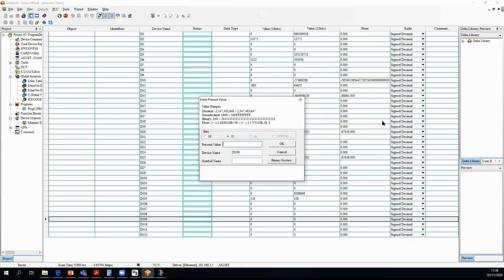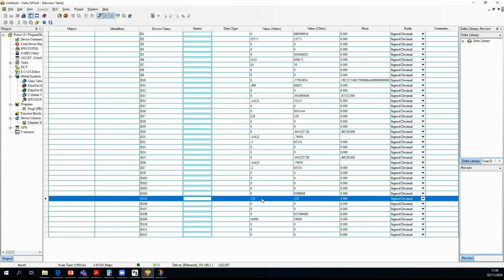So currently the drive is set for a 2500 pulses per revolution encoder. So that means if you have 2500 pulses per revolution, the drive will actually count 10,000 per one revolution. So that's for every pulse rising edge and falling edge. So if I want the drive to do one rotation, I can just set it to 10,000. Okay. So this will be my relative position command.